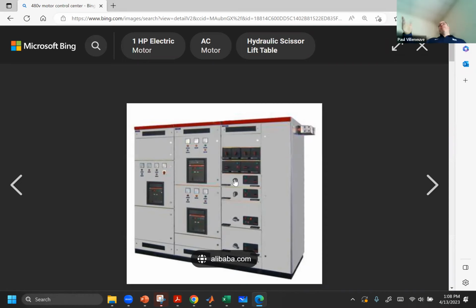So if you have 10 motors or 5 motors you're trying to start, you would buy this low voltage motor control center that would take care of multiple motors and work extremely well. So a starter would basically energize that. The VFD would actually be inside the motor control center typically. It's where you'd find it. And I've seen these things, you can have them 15 sections long. Just go on and on and on.